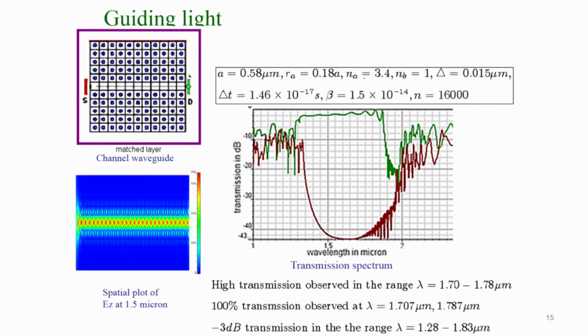So, I will describe some devices which we can make using the photonic band gap structures. One of the simplest things that we can think of, in analogy with electronic crystals, is to create a line defect. You call this a line defect, where these dots or rods are removed in the form of a line. So you do not have holes in this region; holes are removed in the form of a line. This acts as a waveguide. So, a line defect acts as a waveguide for light.